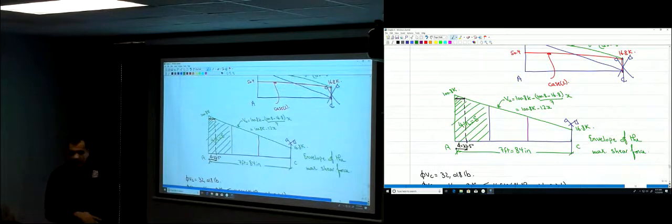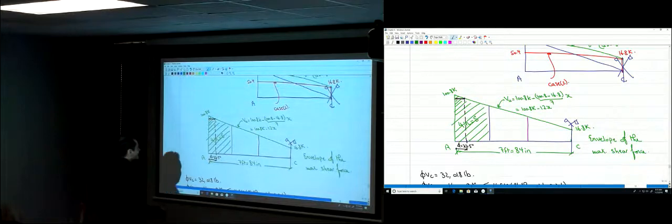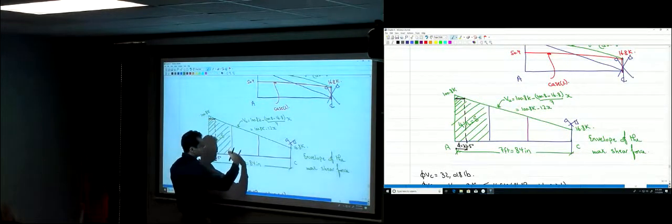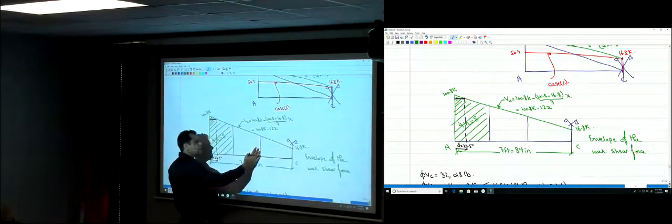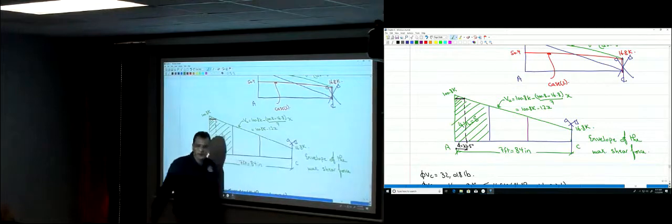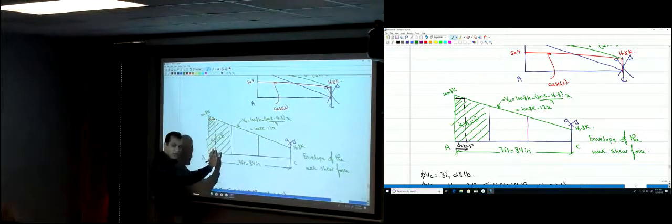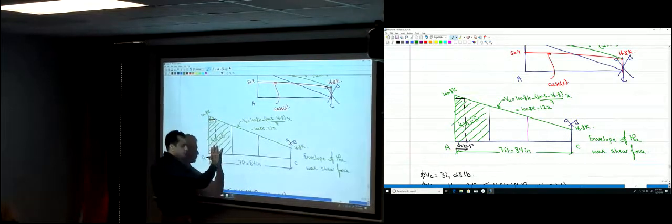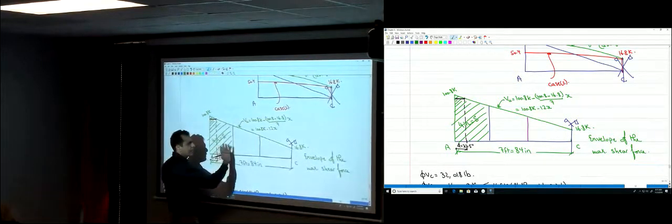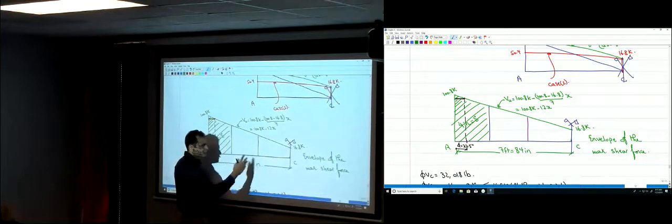And then I will increase the spacing, so I will decrease the amount of steel. I'm going to have another spacing here and then a third spacing here. In the previous problem, we had spacing of 5 and then 9 and then no stirrups. Here we're going to use 4, that's what you need here, and then we're going to increase it twice. You can choose any 2 numbers.